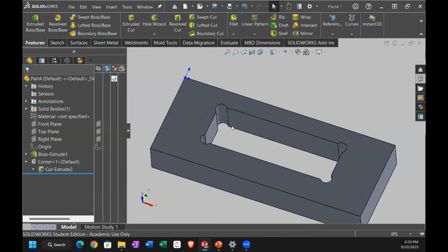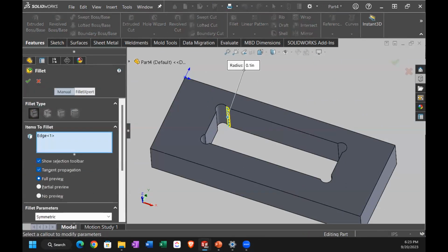And then if you haven't used the context box on the fillets, I highly recommend it. Let's see, I want to do about a 0.5 millimeter, maybe a millimeter. Let's tab, and hey, there's another tab to update your previews as you put in those numbers. Make that a little bit bigger.